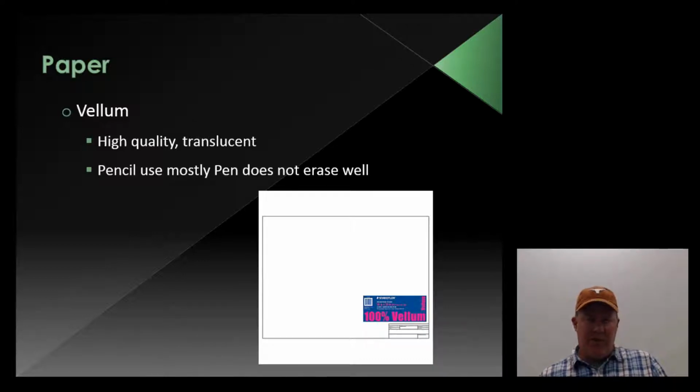I'm not a big fan of the pre-bordered and pre-title block paper. I like drawing my own. I get a little creative and a little artsy with it, and can customize it when I draw it by hand. And I actually draw my borders again simply with a Sharpie or a Pentel Sign Pen. One-quarter inch from the edge of the paper is my border all the way around, and I will either do my title block on the right hand side or at the very bottom, depending on what size paper I'm using and which type of landscape or irrigation plan that I'm drawing.